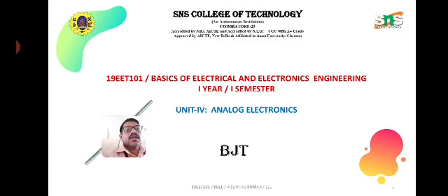Here the BJT, LDR and some simple components are used in order to turn on the street lights when the ambient light is less. When the ambient light is less in the evening time, the street light is automatically turned on with the help of a BJT.